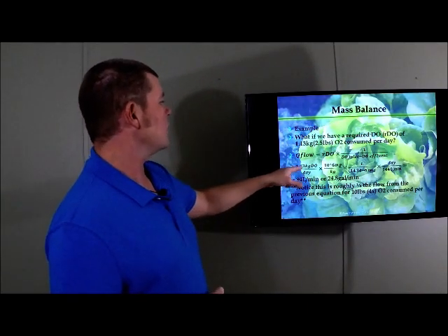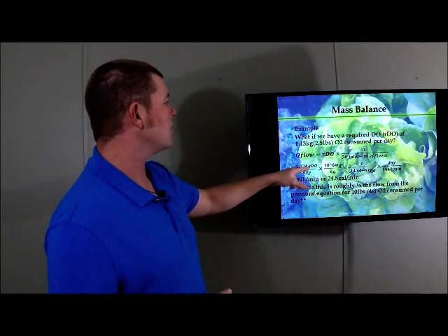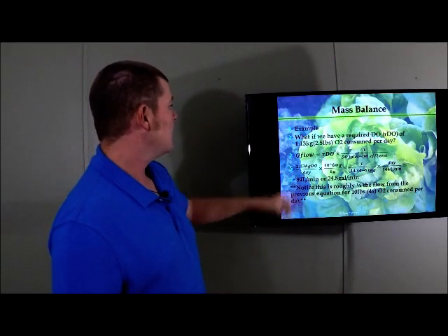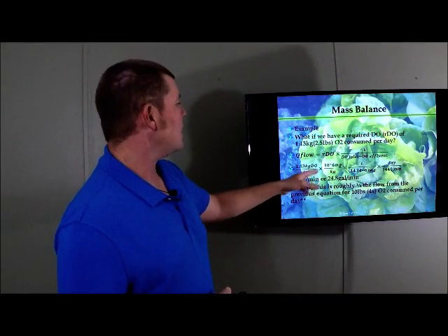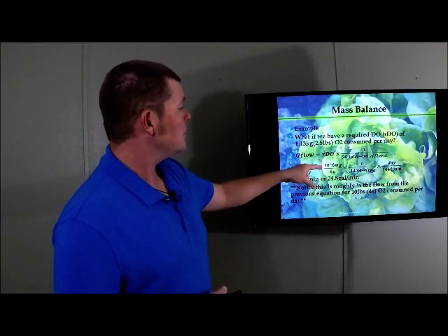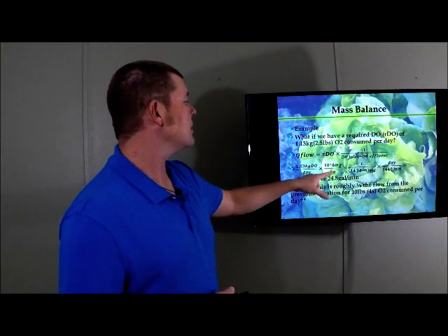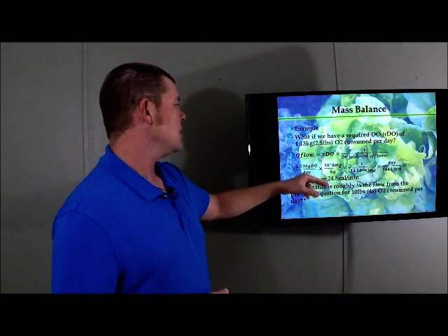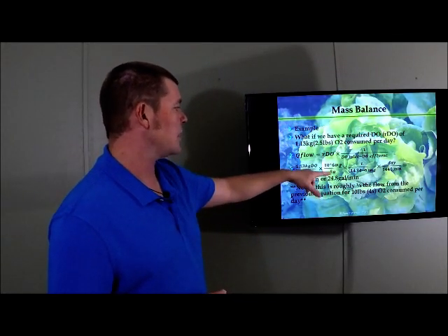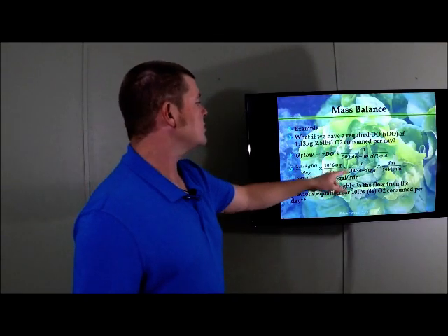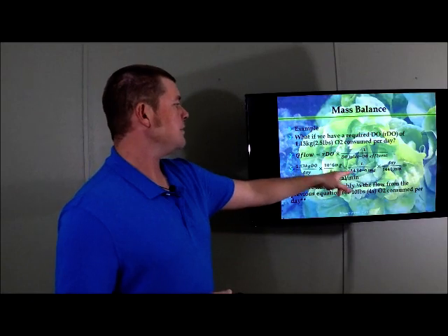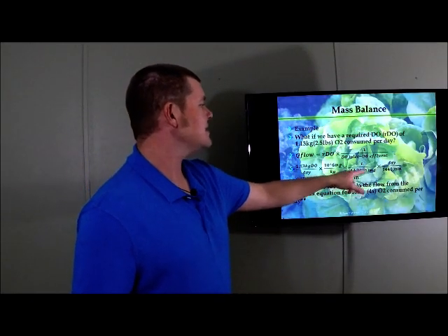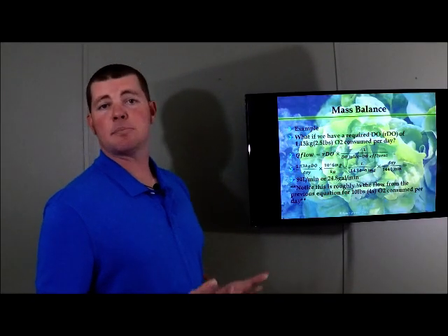We've got 1.13 kilograms of dissolved oxygen per day. That's what we've calculated that we need. We multiply that by 10 to the 6 milligrams per kilogram, so 10 million milligrams per kilogram. We multiply that times liter over 14.34 minus 6 milligrams per liter.